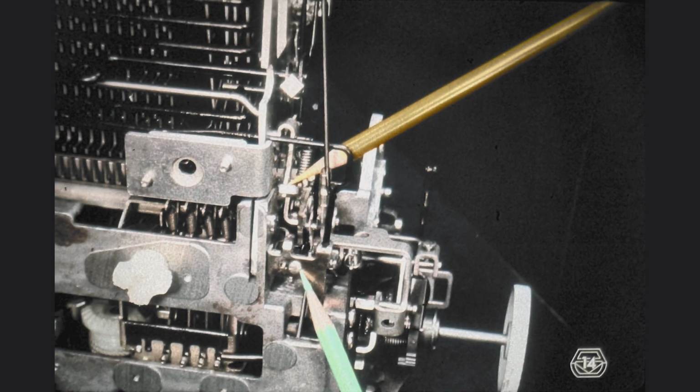When we want to adjust the position of the cam follower, we need to concern ourselves with only 2 adjustments. Whenever, at the point indicated by the yellow pencil, we cause the wire wound envelope of the velocity control cable to move toward the rear of the adjustment point, we provide a longer path, or tube, for the velocity control cable inside the wire wound envelope.